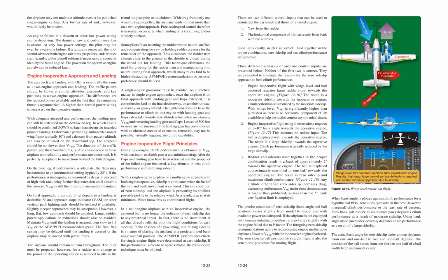Considerable altitude is lost while maintaining VYSE and retracting landing gear and flaps. Losses of 500 feet or more are not unusual. If the landing gear has been lowered with an alternate means of extension, retraction may not be possible, virtually negating any climb capability.